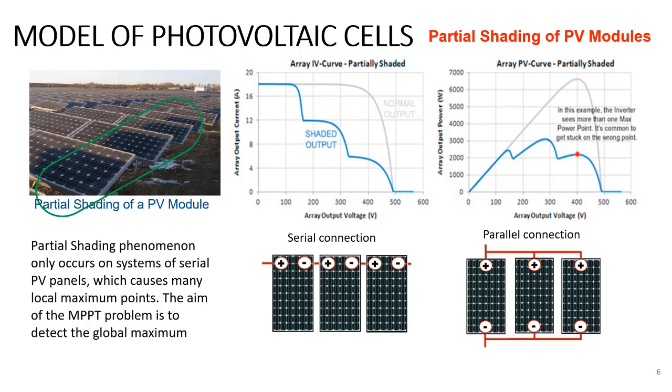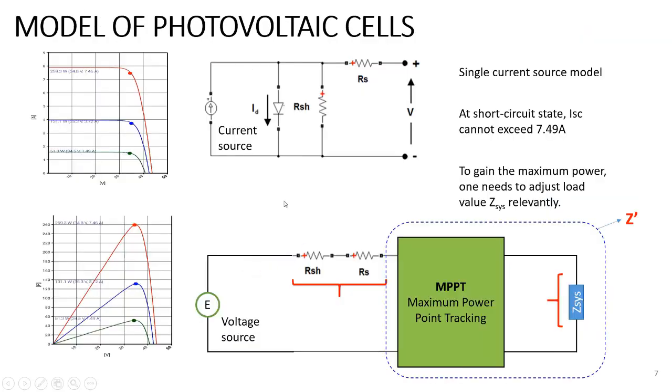To limit this highly accumulative uncertainty, it is suggested to restrict the serial connection between the PV panels, but do the parallel connection instead. This could be explained as the following. When we connect them in parallel structure, if any panels experience shading phenomenon while others don't, all panels can still work with similar output voltage values, although the current or power flow contributed from each of them can be different.